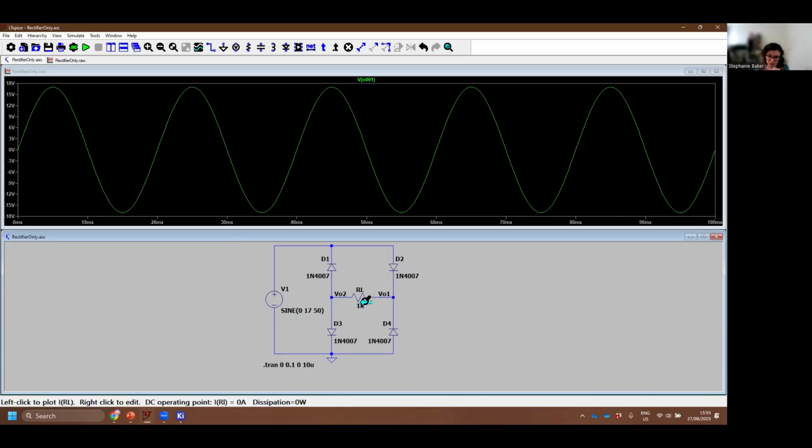Then for our load resistor here, because it's not actually connected to ground on either end, we need to find the difference between the voltage on the top end of the load to the voltage on the bottom end of the load. And it's also worth noting that this is a useful thing to know for when you're measuring physical circuits. Because some sources, like our function generators, are physically tied to earth, so ground is always at that negative rail. Other devices, like most transformers, aren't like that.